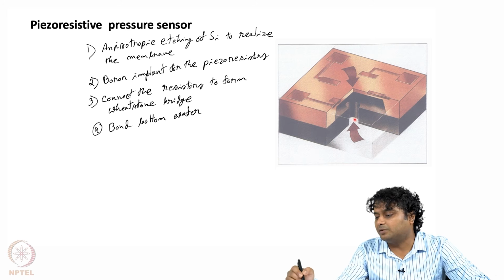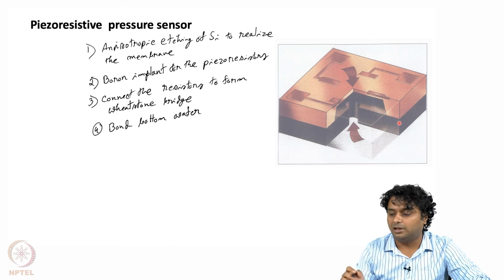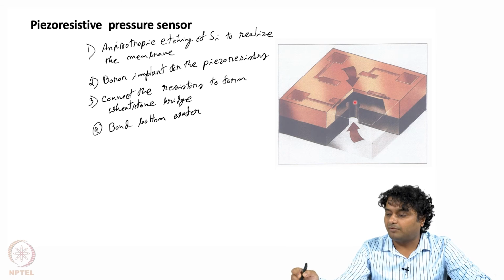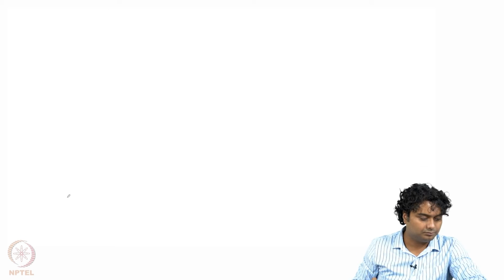We cannot etch material from inside. So, first we make this wafer, and then we separately make the other, bottom wafer, and then we just join them together. You can think of it like clamping two wafers together, and then we have a vacuum or air trap space in between, which will be trapped gas, and the top or thin side acts as a membrane. Now, we will discuss how we can make it.